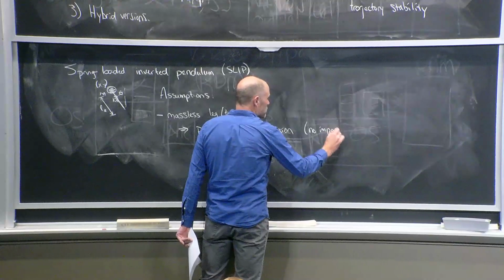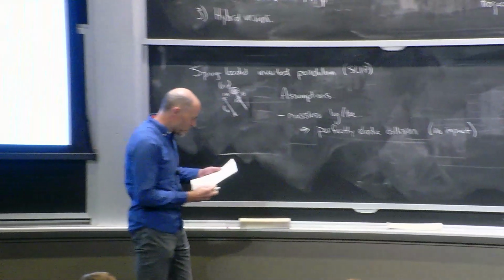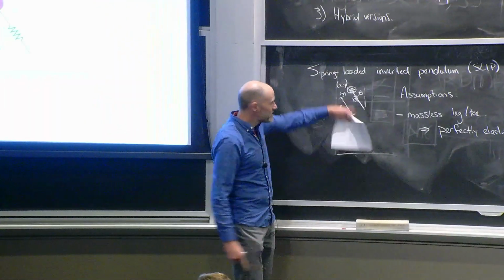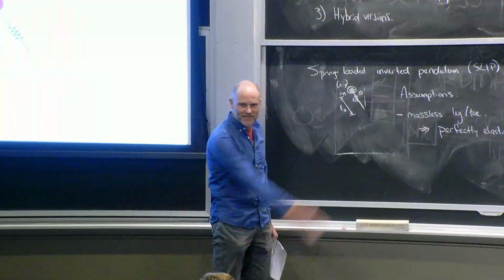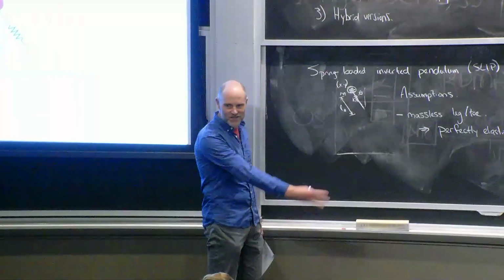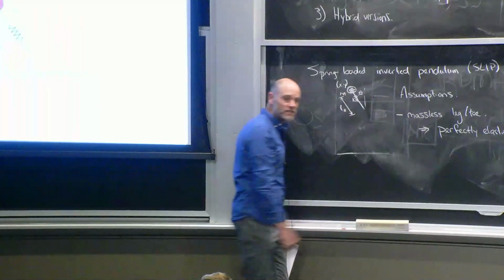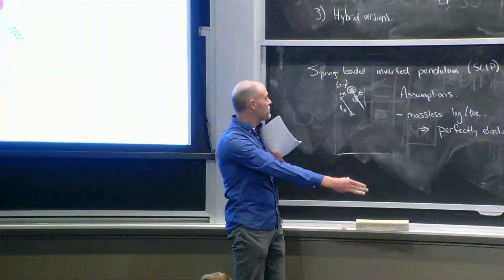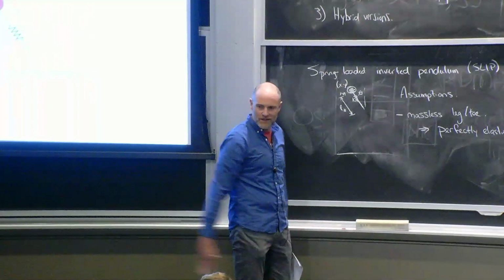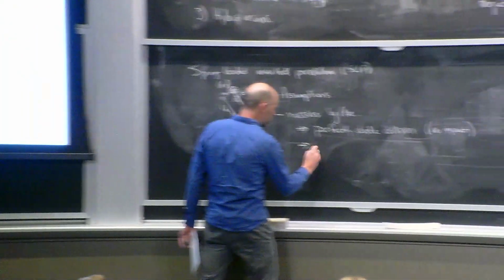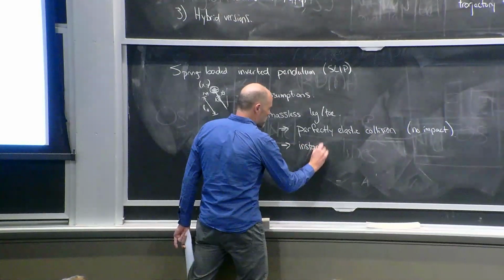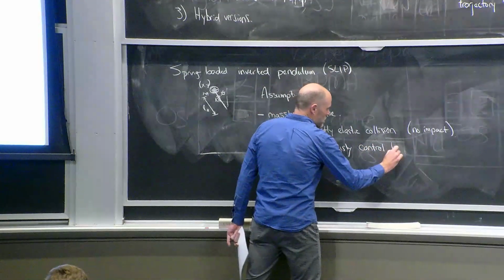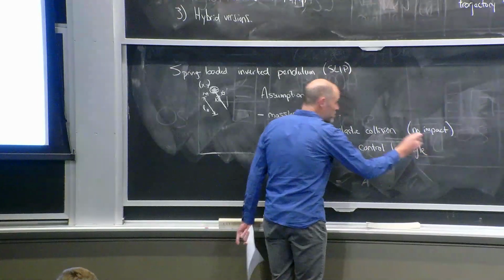No impact. Okay. Also, if you have a massless leg, then basically you can reorient your leg angle instantaneously, which is of course nonsense, but that's the abstraction here. In the limit of the mass going to zero, instead of thinking about torque control for the hip, we can just think about commanding the angle of the leg, at least when you're in the air.